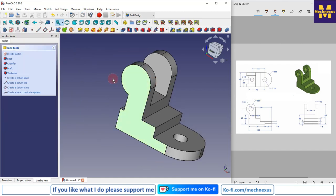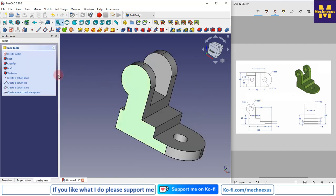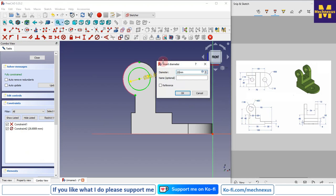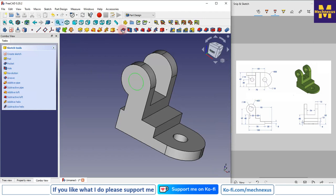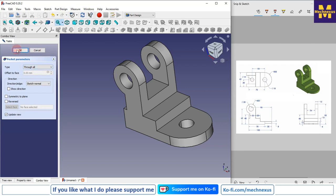Now I will select this face and create a sketch on this face, and this is a diameter 20. I will say close and extrude cut and through all, say OK.